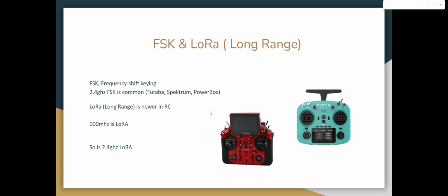The only problem we've run into is not the problem with the hardware. It's the problem with the actual RF environment. It's gotten worse over time, actually much worse over time. So there are things out in the fields occasionally, like for example where Flight Fest is located, there's an oil well out there that about every 10 minutes or so broadcasts on 2.4 gigahertz how much oil it happened to pull up, and if you happen to fly through that signal as it's being broadcast, it swamps the plane and down she goes. So that's called signal swamping. That's one of the problems. It might happen for a second or two, but it might be the difference between flying and not flying your plane anymore.